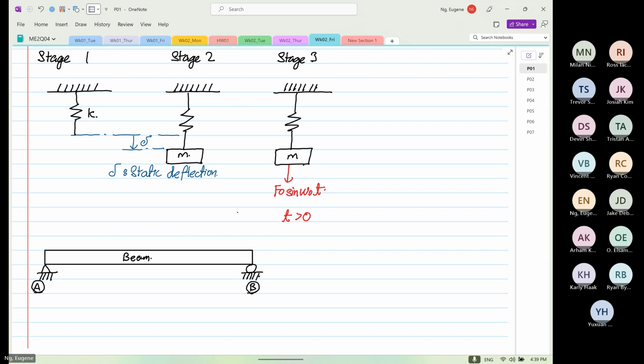So for what I'm going to do, because I'm so used to writing displacement in the X, I'll call this my X and I'll call this my Y. Okay. My X, my Y. And we know that at point A, because it's a pin, X is equal to 0, Y is equal to 0.